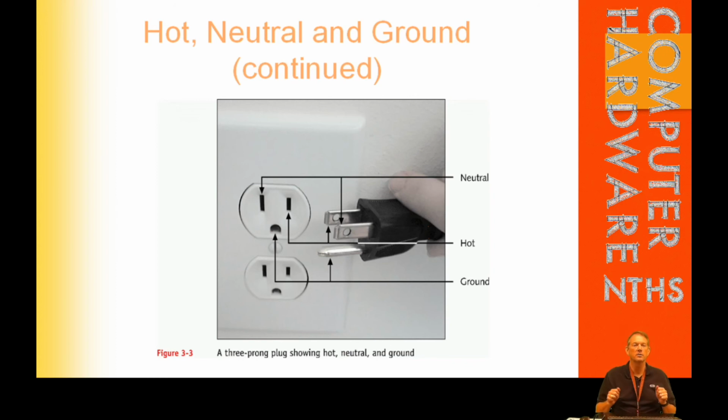Last thing I wanted to point out is what the plugs of this are for. If I look at a plug, there are 3 different things on a normal plug, just like this picture. The one on the bottom is the ground that has no electricity flowing through it whatsoever. It's important to know whether your house has a good ground, because if it doesn't, then this doesn't do anything. And neither does any of our power protecting devices that we're going to talk about later in this chapter. So the ground goes through, and then one side of this is neutral or return, and one side is hot, or the one that actually will shock you. So 2 of these plugs, realistically, don't do anything to you. The third one, the hot one, is the one that's traditionally smaller.